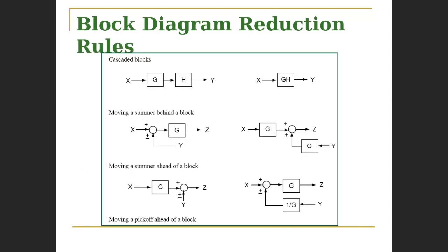So when I speak of block diagram reduction techniques, I'm talking about rules that govern the reduction of block diagrams. And there are about 6 of them. We'll start with the simplest of the rules. Now, the first one speaks to cascade blocks. And when we hear about cascade, what should come to mind is series, blocks in series. All right, remember that